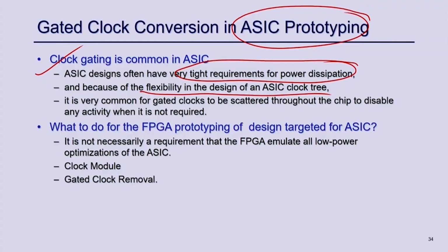And now, think about a circuit of that scale that has a lot of clock gating, and you try to put it in an FPGA. Then this clock gating will create a serious problem, right. You cannot map all those clocks to the FPGA board. So, the main thing the FPGA synthesis tool tries to do is gated clock removal. It tries to remove the gated clocks from your circuit, so that the whole design can be synthesized from RTL, because if you cannot remove the gated clock from your actual circuit at this point, then the whole purpose is lost, right.